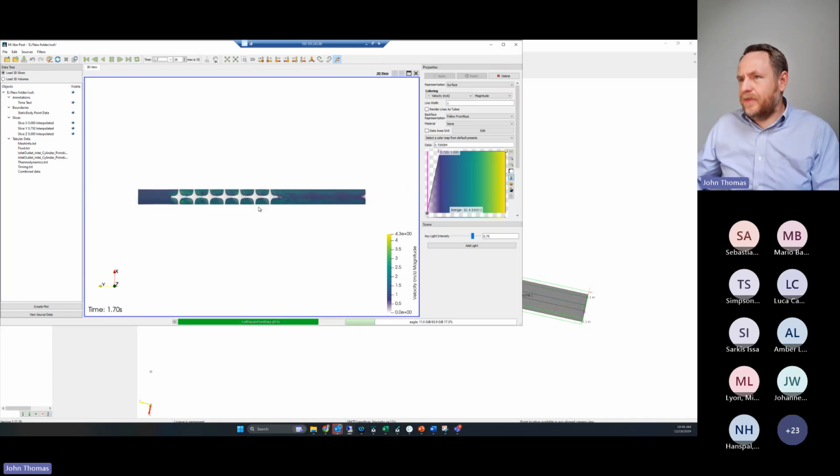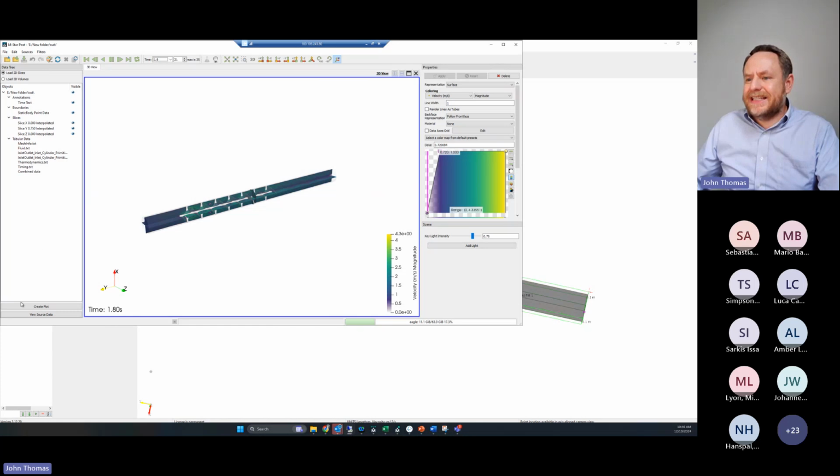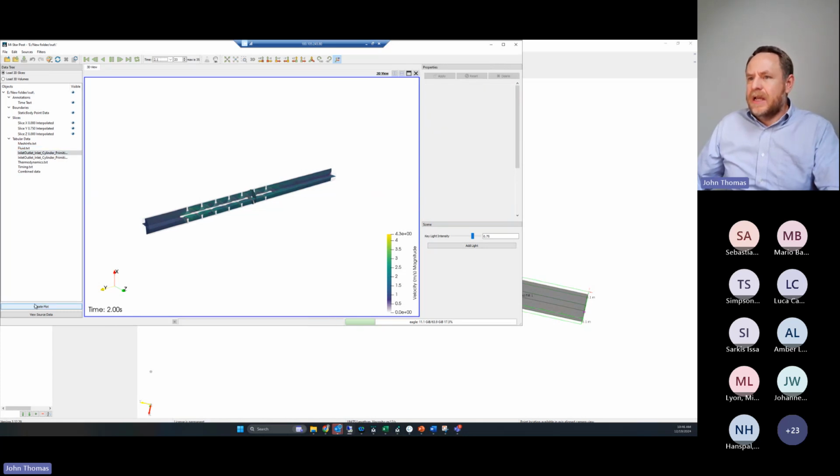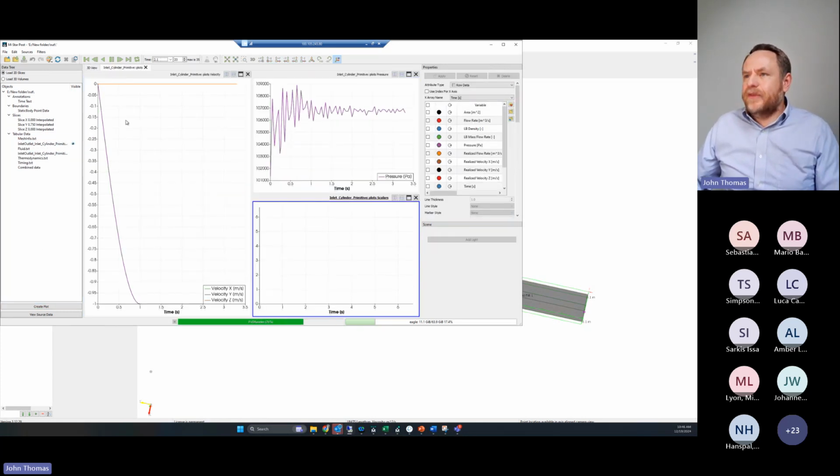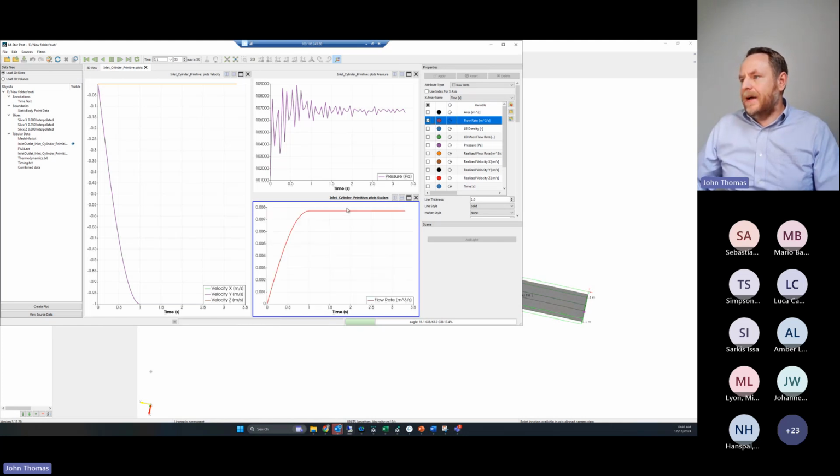But to be sure, there's just my flow there. As I go through this, I can see some characteristic data here. I'll also look at my inlet. I can see that my velocity ramped up, reaching steady state flow conditions after about a second. And my flow rate here was about 0.0077 meters cubed per second, about 7.7 liters per second.